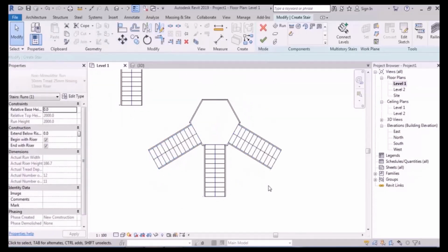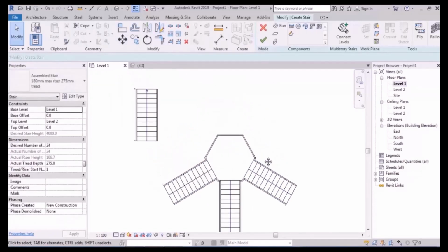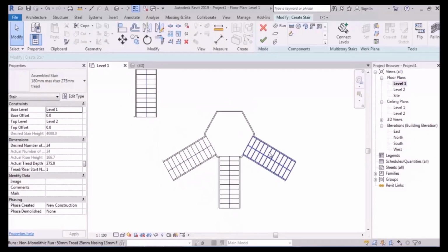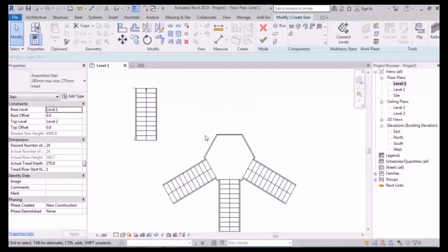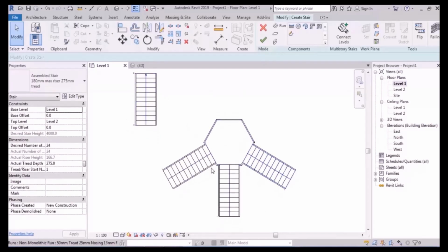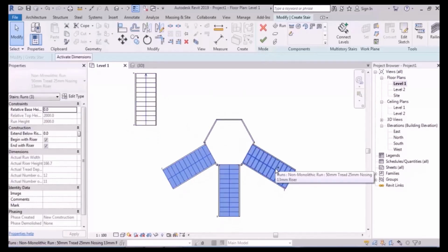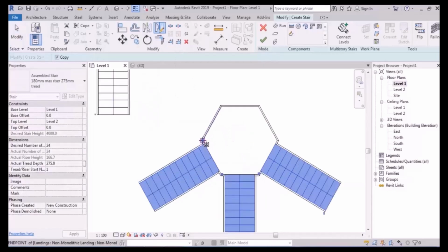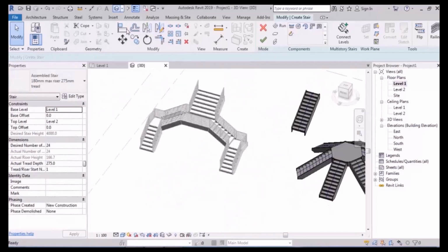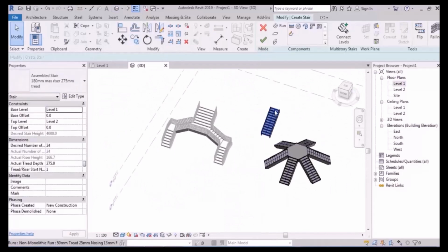Right now, a lot of people make a very big mistake. They actually say, why do we bother? We got 3 runs here, we can easily mirror these 3. Which is definitely wrong, because now they're at the bottom. It's the other one which is at the top. And you can't mirror these, because if you do this, it will be more like a platform rather than stair. So we must use this one.